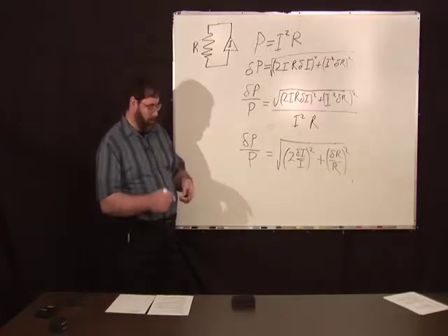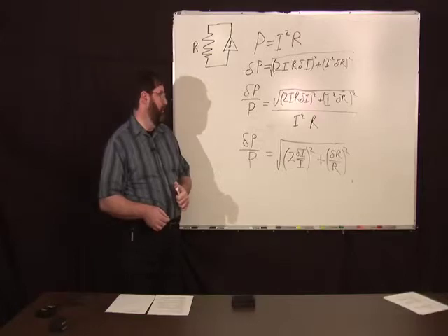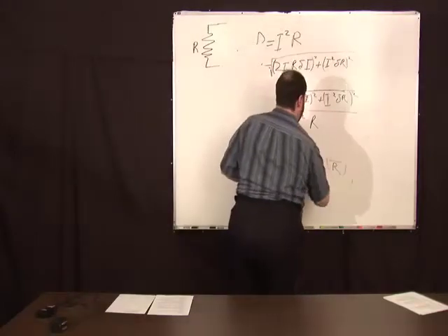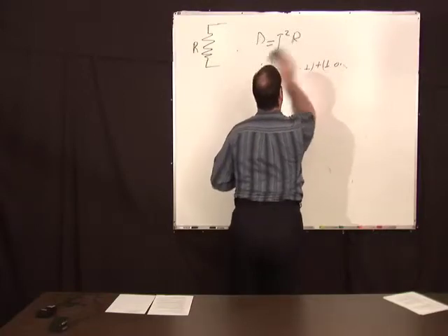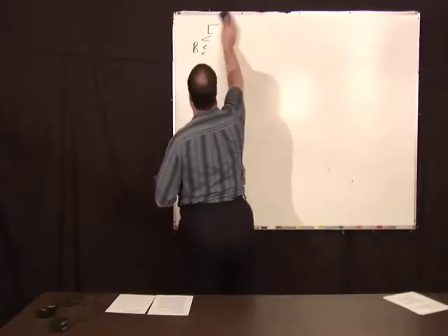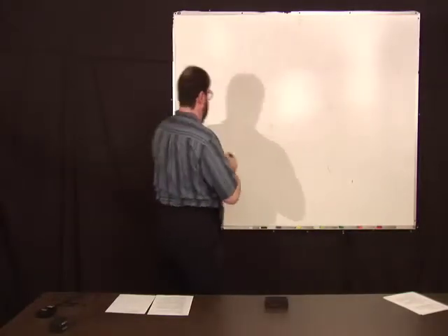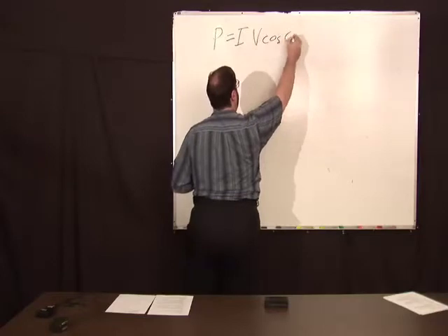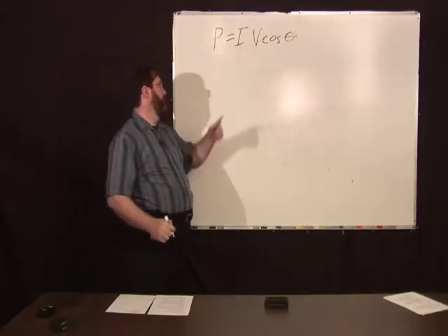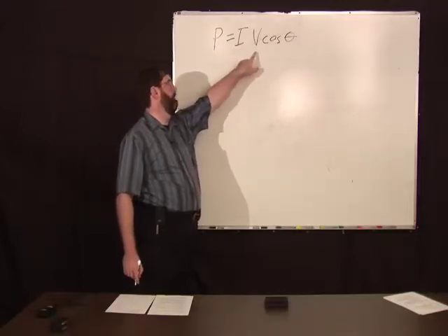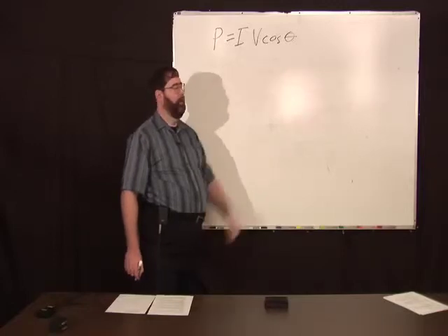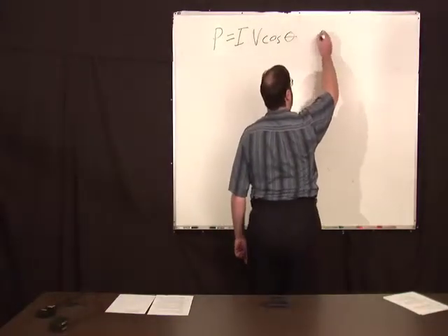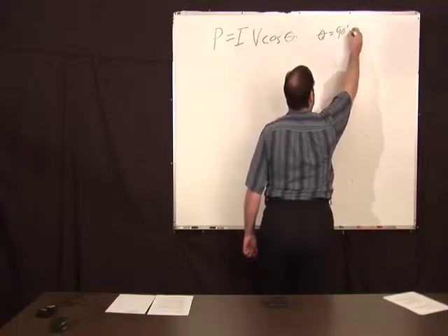Now, there are examples where this type of analysis would break down. I'll give you one. Let's say this is not you want to measure the power delivered to a resistor. Let's say you want to measure the real power delivered to a load, P. In this case, AC power, the real power delivered, is the current times the voltage times the cosine of the angle between them. Let's look at the particularly interesting case where you measured theta equal to 90 degrees, or pi over 2 radians.